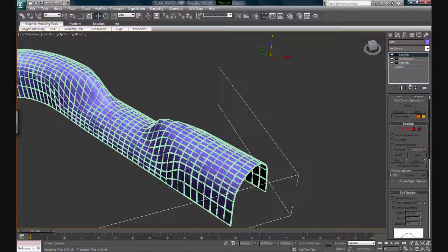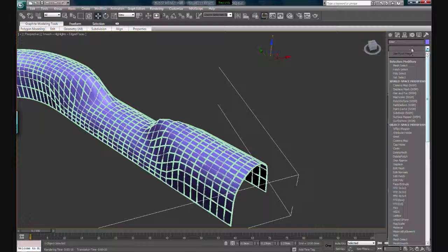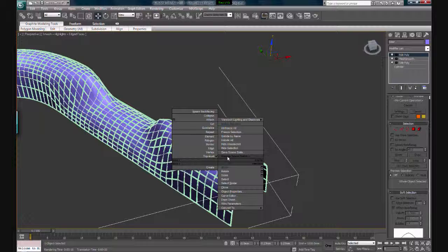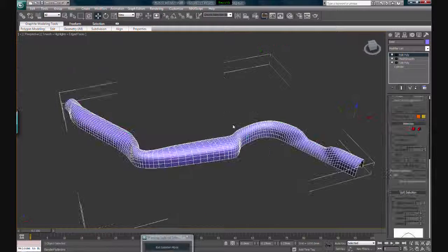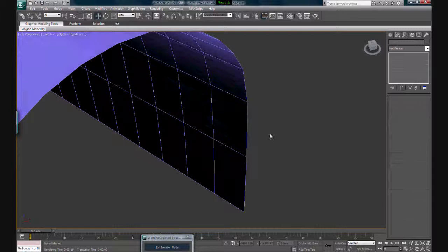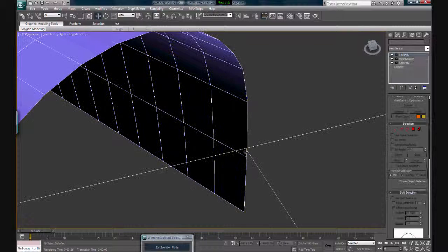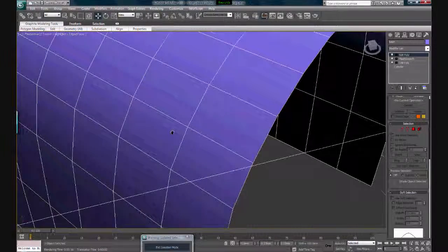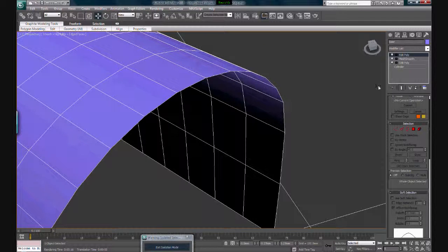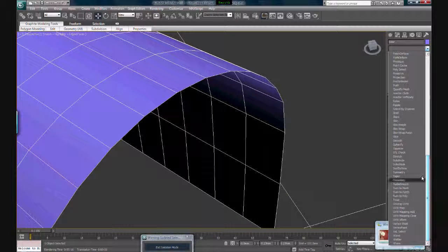Alright, so for this tutorial we're just going to transform the base into glass panels. I'm just going to go to the edit modifier list and apply a modifier called shell. To have a better view, I'm just going to isolate the base model, isolate selection. Right now our base is paper thin, because it started out from a cylinder and I gradually deleted some of the faces, so it becomes paper thin. To make it solid, we have to apply a modifier called shell.